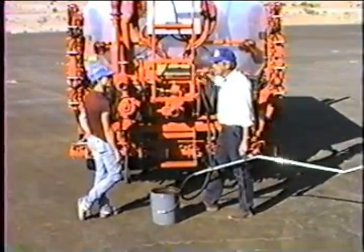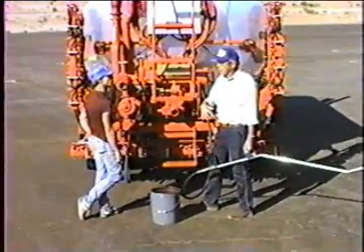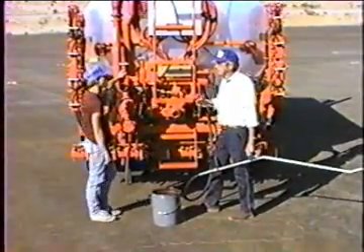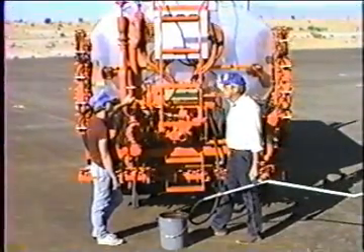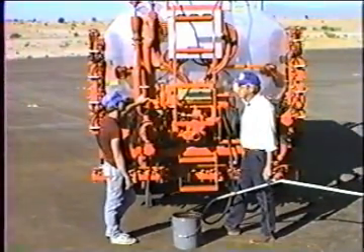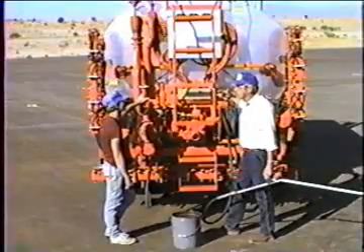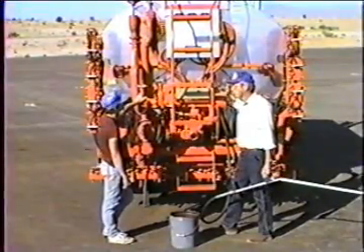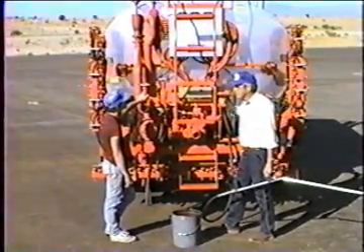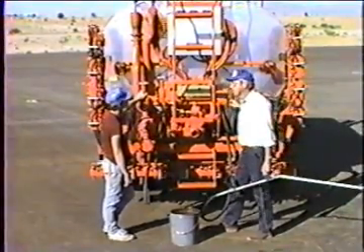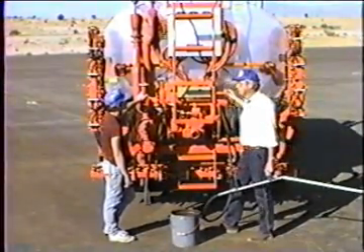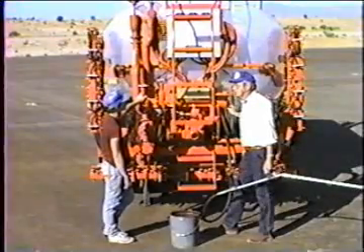It'll knock that flash point down, whereas pure paving grade asphalt should flash at 550 degrees. If we put a gallon of diesel into this 2,000 gallons of paving grade asphalt and they do that test on it, it'll flash at maybe 250 degrees, just because of that little bit of diesel in there as a volatile that will burn. And then they say, well, you didn't bring us paving grade asphalt, and so you don't get paid for the load.